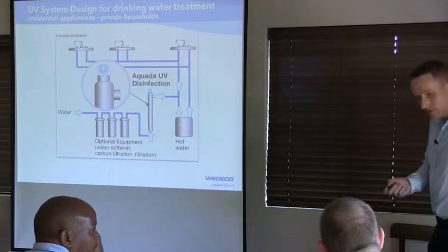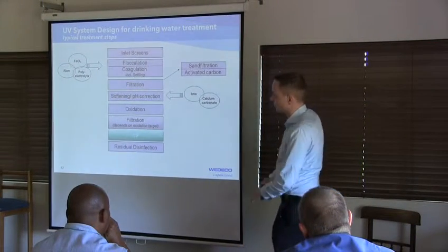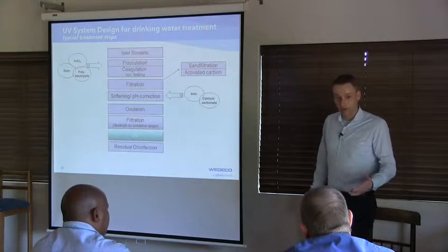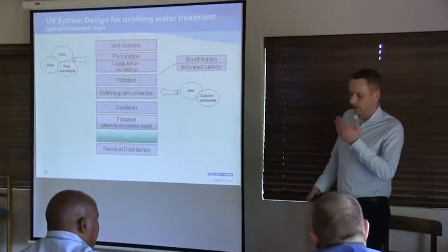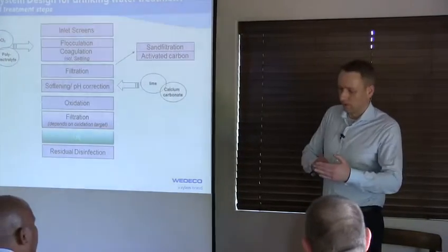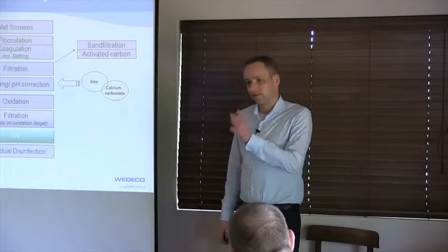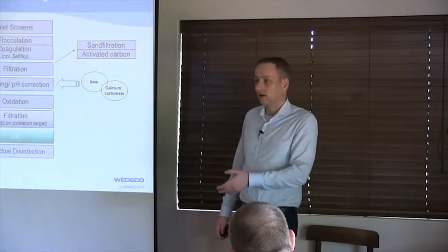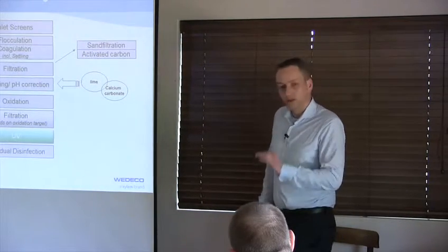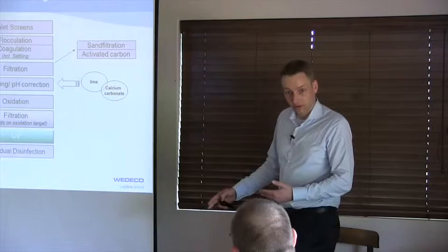Sorry, is that necessary? The chlorination after? The chlorination after depends on your distribution system. The thing is, UV is working on the spot. It doesn't build up a residual in the water. So if you have huge storage tanks and if you have a long retention time between the disinfection process and your end customer, then you might have the formation of a biofilm inside your piping or inside your storage systems, and then normally small amounts of chlorine are added to have this long-term residual.